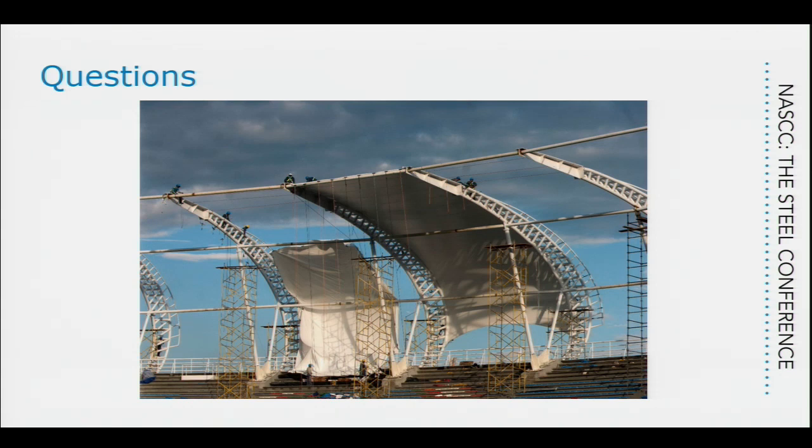Okay, something that we can cut away once we have it in place. Because what we don't want to do is put a patch of material and reinforce on a membrane that is very dependent on, if we establish a form finding process and a cutting pattern, if all of a sudden you come back and reinforce a portion of it, you get a part of the structure that behaves differently from what you thought it was going to. So any reinforcement and lifting that we need to do, we do it exterior to the material that we have.